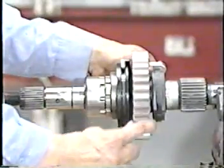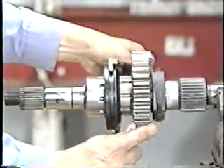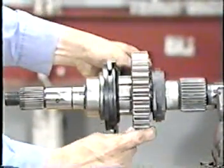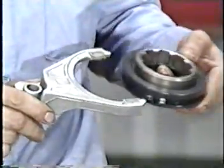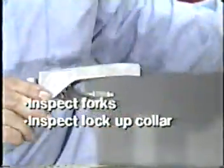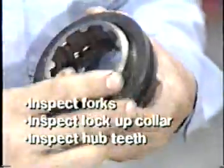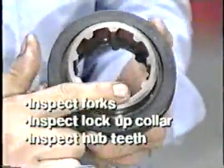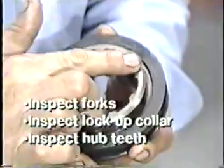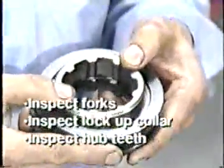The mode shift fork controls shifting from two-wheel drive to four-wheel drive. It works with the lockup assembly. There are 3 main things to inspect on these 2 sub-assemblies. Inspect the forks for wear and condition. Check the lockup collar for damage. Inspect the hub teeth and snap ring for wear. All these parts look good here.